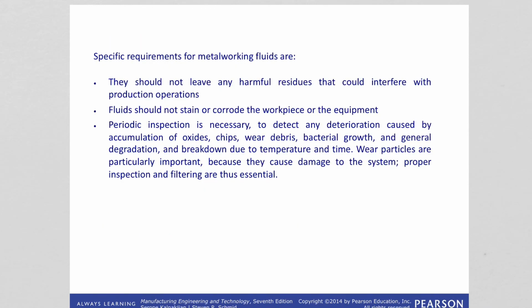When we are looking at metalworking fluids, we need to make sure of certain things. First, they should not leave any harmful residues that could interfere with the production operations. Okay? And the fluids should not stain or corrode the workpiece and the equipment.